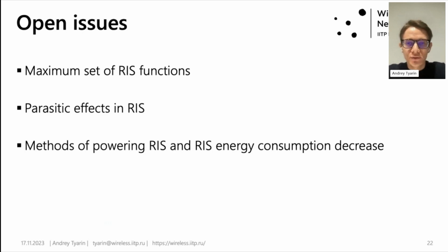Most papers related to RIS prototyping pay no attention to various parasitic effects. And individually, each of the parasitic effects already has a significant influence on the impedance of the unit cell. Parasitic effects can be caused by solder, for example, on contacts of the tunable chip, or mismatch between the originally specified sizes and the manufactured ones.